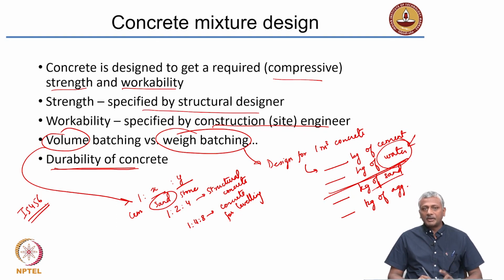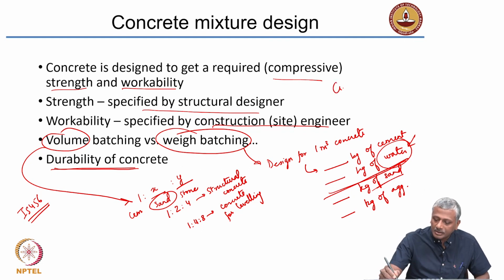But with respect to durability, if we do not have a clear understanding of the environment and what can happen in that environment, we could be in for a lot of problems with respect to the concrete structure. So, today increasingly the focus is shifted to durability, and because of this there is one more additional person that needs to come in for large projects, and that is a concrete technologist.